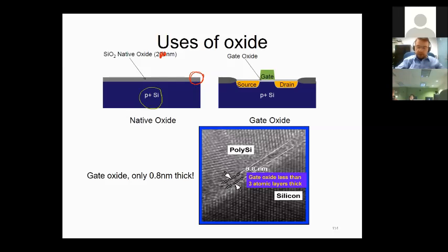As for the other types of the oxide, we've talked a lot about MOSFETs, right? We said that they were our switches, so we could conduct or not conduct based on the third electrode that we had on the gate. So with respect to the voltages, we were enabling the conduction or not. In this case, this transistor, as the fundamental block of all of our computation and all the science today, we need to have super good high quality gate oxides just underneath the gate.